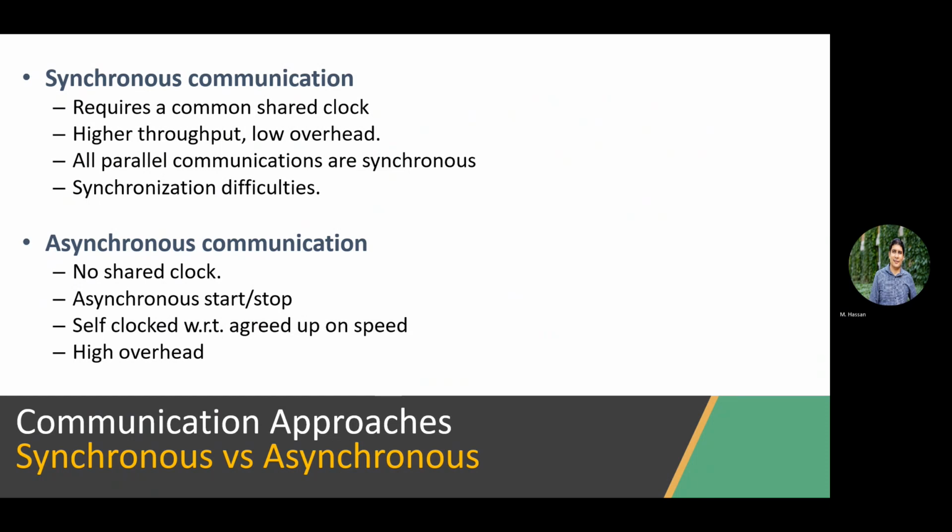Yeah, so what you said first is correct, but the subsequent argument is a little bit not true. Think of what happens in a serial bus. In UART, for example, you need to send: this is my start, keep sending data, this is my end, correct? This is okay for serial communication because it's serial, which means the start bit definitely will arrive first, right?